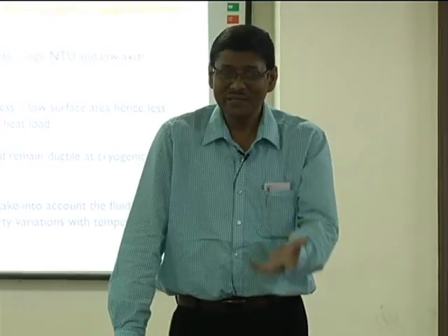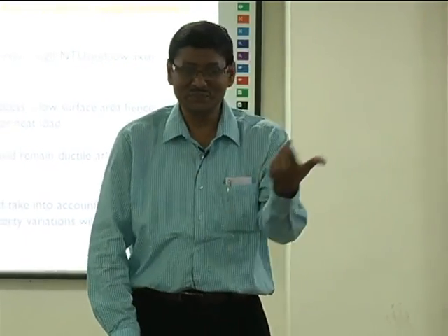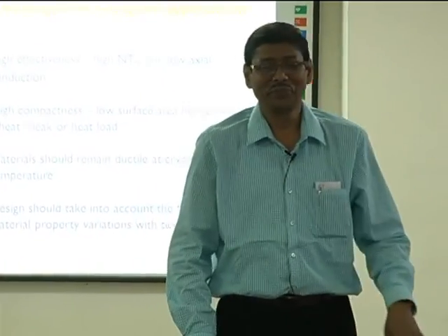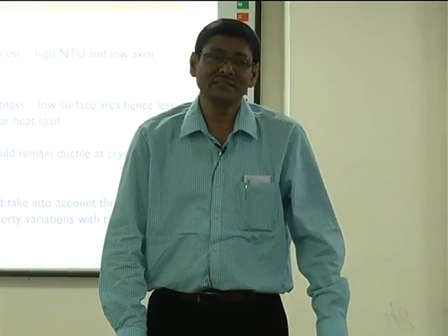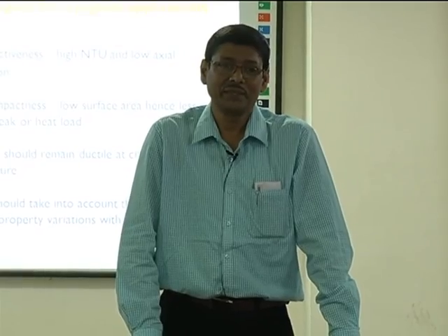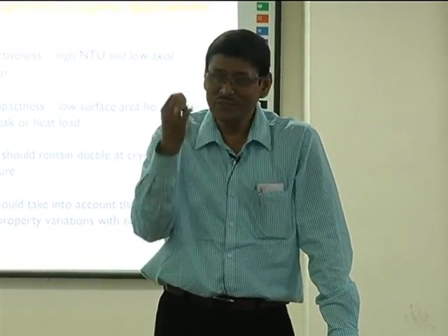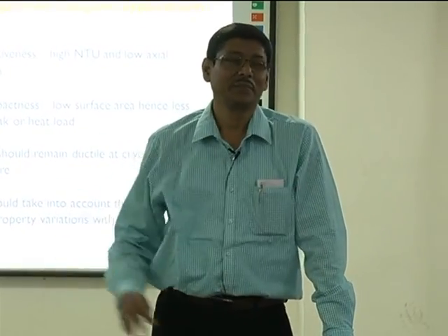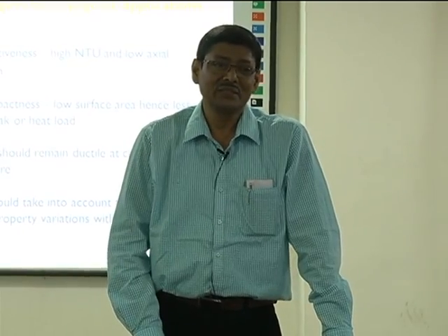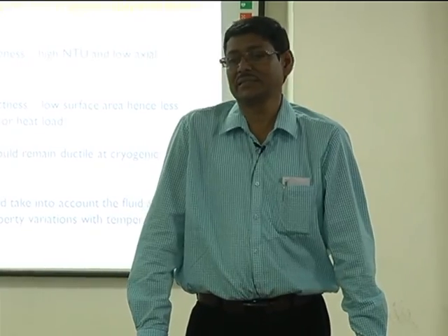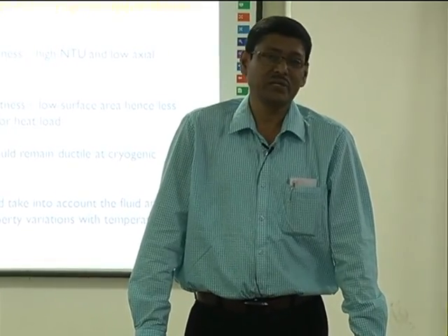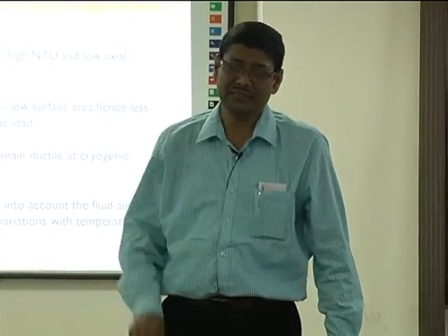Normally in chemical industries we talk of 60%, 70%, 75%, no problem. But in cryogenic cases, if the heat exchanger effectiveness is less than 85%, then you get zero liquid output, no liquefaction. So that means what? It says that you need high effectiveness heat exchangers, or very top quality heat exchangers, for cryogenic applications.